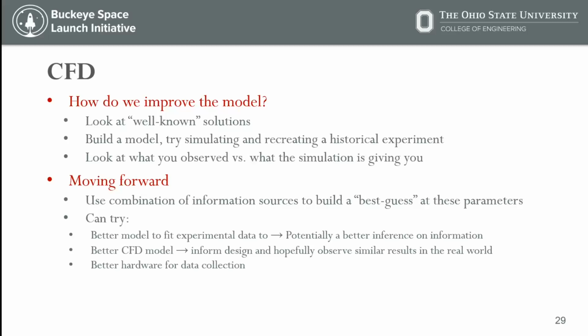I can speak for our flight computer. The TeleMetrum only has a one-axis accelerometer. It only looks at the axial acceleration. So if you're turning and you have a significant side slip over your vehicle, you might be going up, and your velocity vector might be 10 degrees off vertical, but your actual orientation might be 11 or 15 degrees off vertical. Now your axial acceleration is not indicative of what's actually happening. So you're going to have to look at your equations of motion, look at the model that you're building, and try to fit that data to that model.